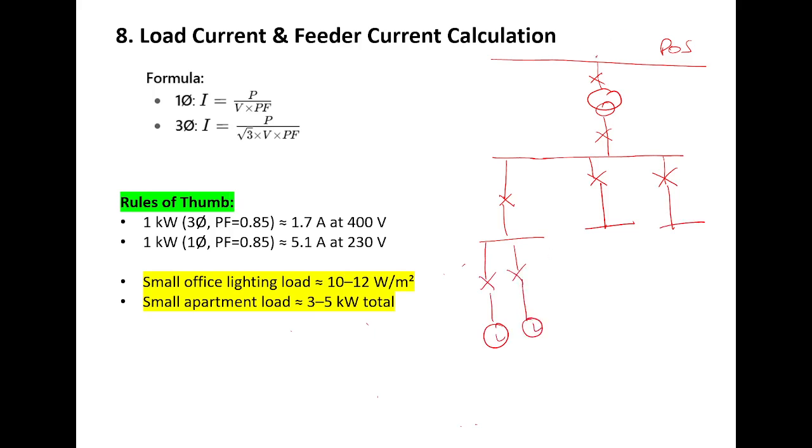Like this. Okay, so you can see here, this is my point of supply from where I'm getting supply at 11 kV. At 11 kV my electricity is supplying from this point to the primary side of the transformer, and this transformer is stepping down the voltage. Let's suppose I am getting 100 kilowatt of power from here at 11 kV, the same power I will get here if I am neglecting losses. So 100 kilowatt of power, but at 0.4 kV. The voltage level will decrease. As the voltage level decreases, the current level will increase, obviously.